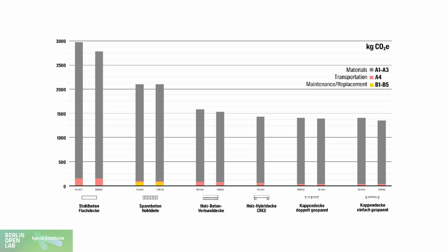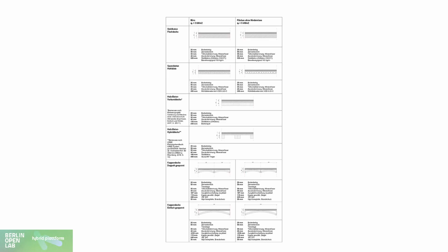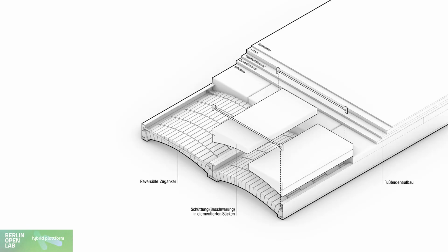The great thing about the cap ceiling, as it is made of masonry, is that we have a significant mass, but it's not concrete. And you can also bring mass on top in the form of some kind of heavy material, like gravel or something, to meet these sound insulation requirements. We also published these comparison studies quite recently in a journal article. And that's one thing we thought: we found out it could be a good idea to build cap ceilings, but what does it take?